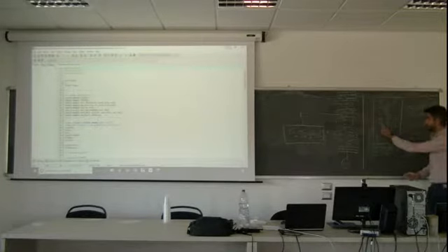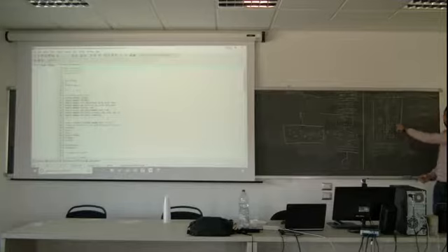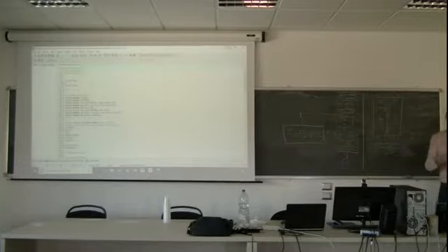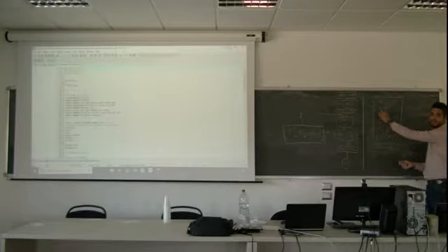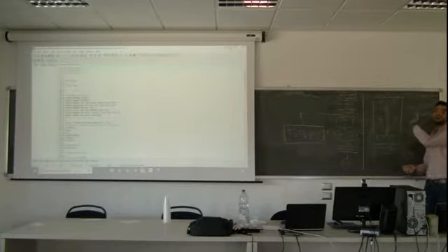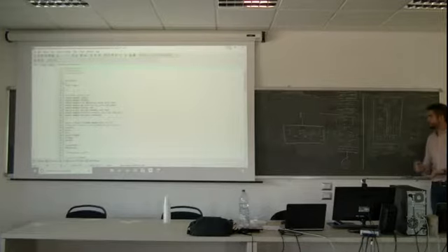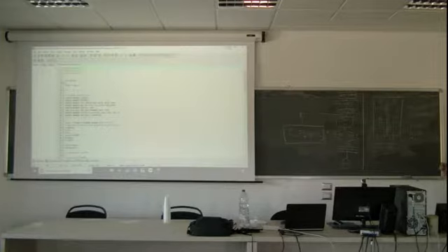So the dimension of the node here will be 5 millimeters, and here it will be 10 millimeters. Correct? Because the thickness is different. I know the drawing is not very good, but this is 5 and this is 10. Okay? 5 and 10. So you can change. And why? Because here we have generation of heat, so we will have more gradients here than in the other part. That's why I added more nodes. This is just an example. Usually I will use more than 10, but it's okay just to show. Okay?